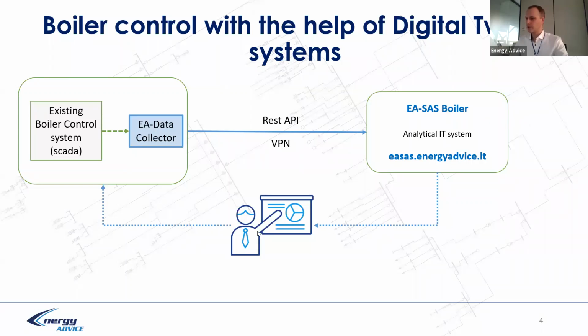And we can provide feedback to the control system, maybe through operator, the optimum fuel supply, optimum air supply, primary, secondary supply, and this would be like set points to the SCADA system where operator just put the data from one system and enter to the another system.